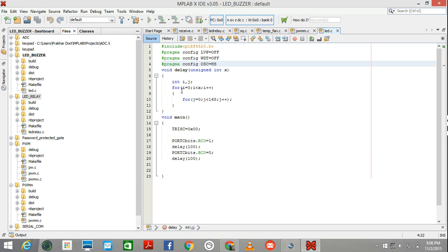Okay, let me think of an easy way to explain this. See, if there is a certain position or certain state that my microcontroller is functioning in right now, and I want that state to be held for a certain amount of time, then after declaring that state, I'm going to call this delay function. That means my code will be running in this nested for loop again and again, as long as this condition is not false.